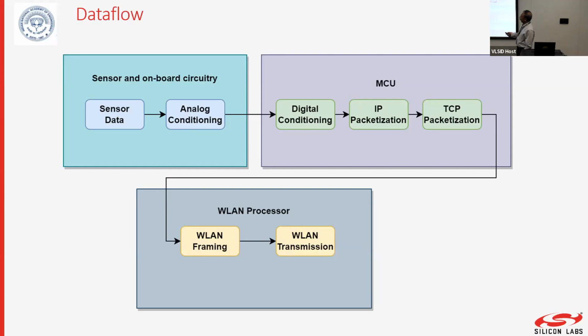All right, so sensor data you need to condition in some way. You might get a few millivolts. You can't do anything with a few millivolts of data. We used to do a lot of things with a few millivolts of analog data a long time back, we used to take decisions on them also. Today nothing can be done unless it is digital data. And before you convert to digital, you need to condition it, because the more you eliminate at the analog level, the less is the uncorrectable noise that comes into the digital level. So analog conditioning is important, at the very least amplification and filtering.